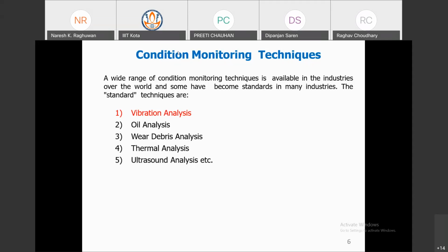Initially the oil is fine when you fill it, and after that it becomes like black oil. So you analyze whatever foreign particles come into the oil. Suppose a gear tooth is missed and falls down into the oil. We analyze, and if some foreign particles or a gear tooth are there, we can say the gear tooth is missing, and that is why the condition of the gearbox is very critical.